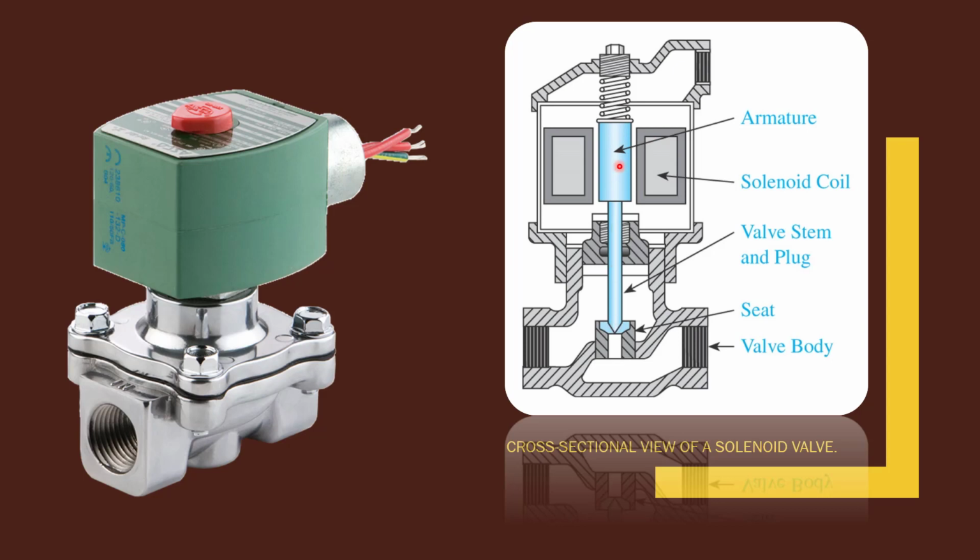We're going to move this with an electromagnetic field. We've got this spring that's pushing it closed, but if we create a magnetic field in this coil, that magnet will cause this thing to move up and gas will flow, or whatever, or fluid. Then once the coil is de-energized, the spring will shove it closed again.